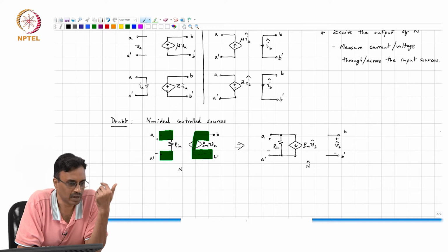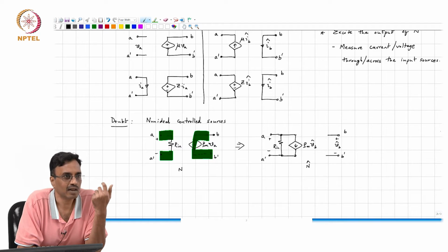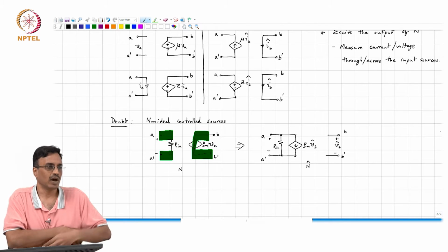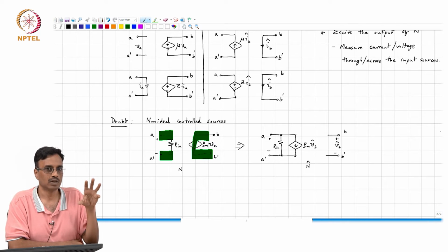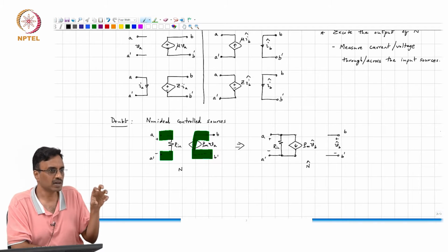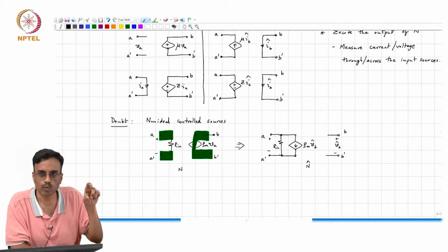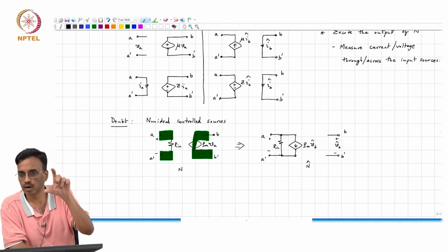Some of you may also be aware of a less known feature of SPICE, namely transfer function analysis, right? How many of you are aware of the AC analysis? Everybody is aware. And what does the AC analysis do? You have how many inputs and how many outputs? You have one input, and you can click on any node and find the frequency response from that one input to the output, correct?